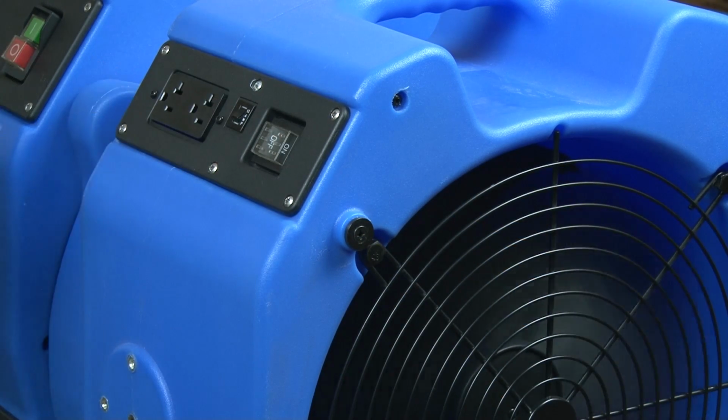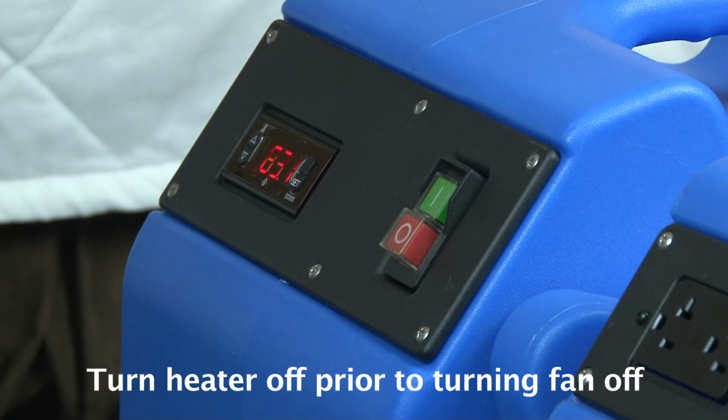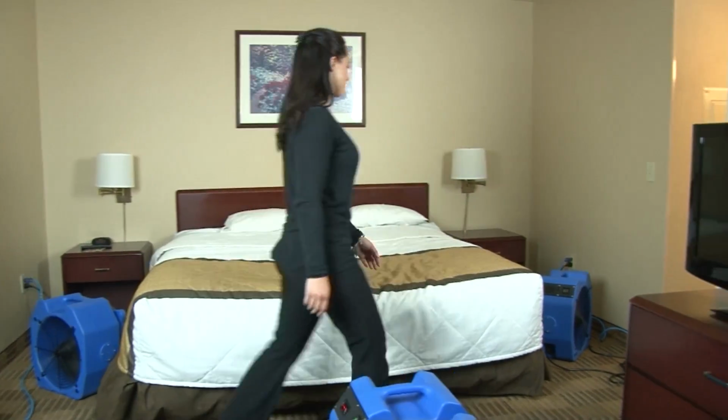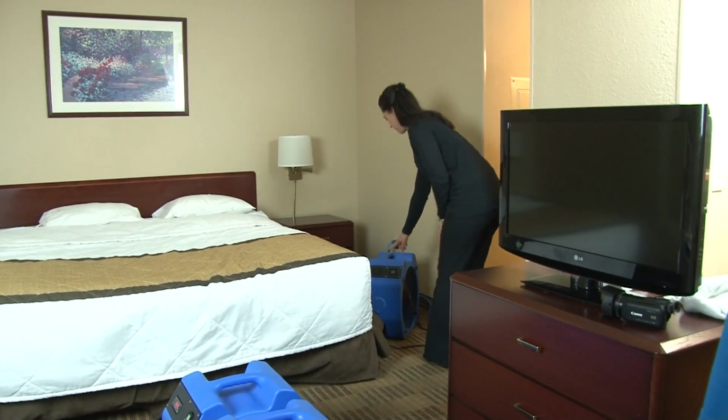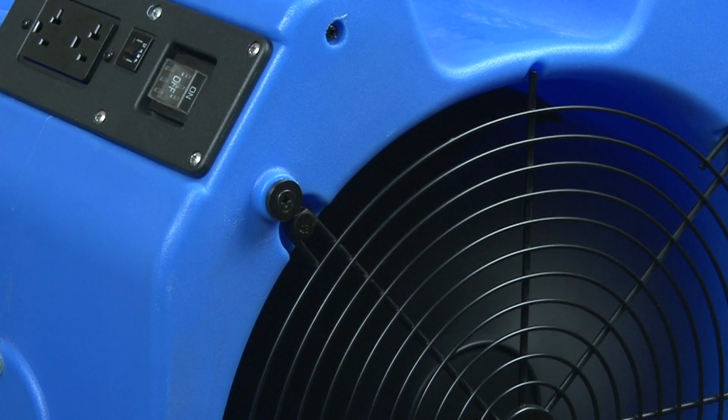Caution! Always turn the fan on prior to turning the heater on. Always turn the heater off prior to turning the fan off. Now, turn on the rest of the fans and let the process run for a minimum of 18 hours. Be sure to check the system from time to time during the process to make sure no breakers have popped and to turn the fans in different directions.